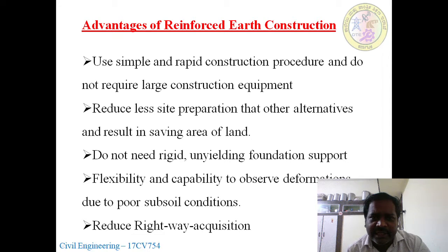Here we are providing the strips, the mesh, and the linings for the soils at different spacings in the horizontal as well as the vertical directions. The spacing depends on the design procedure. There is no need for any construction equipment for the construction of reinforced earth, and it requires less site preparation than other alternatives, resulting in saving of land area.